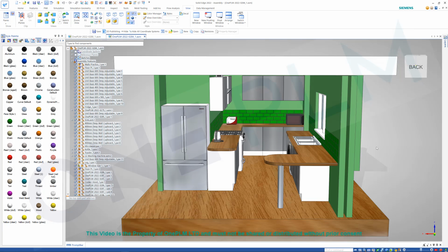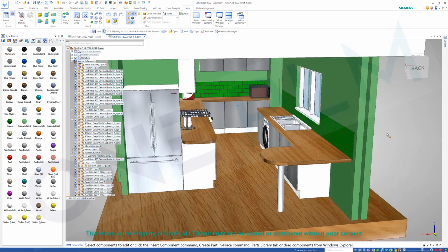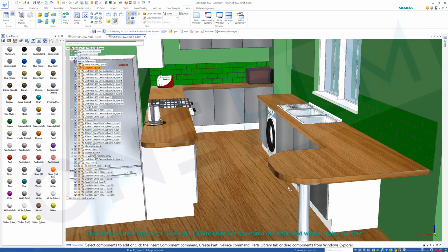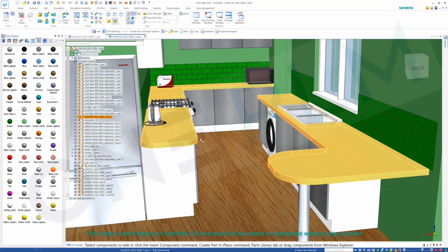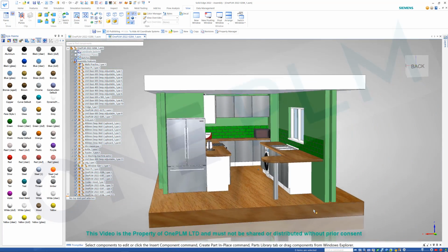This may take a few seconds, so just give that some time. And then I'm also going to go to sharpness, that's on 2. I'm going to go up to 4 on there. That means that we're going to get improved visual on there again. Wait a sec for that to improve, and then it will start to calculate. You'll notice the edges will be slightly square or faceted, but as soon as we go in, everything will start to be smooth again.